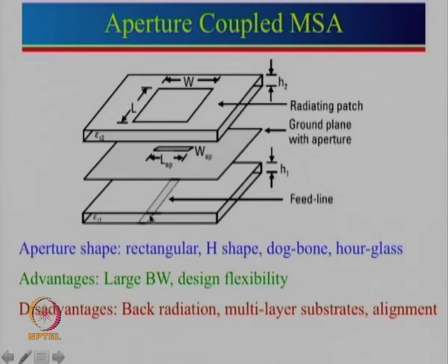So, now let us see what is really happening one more time. This is the microstrip line, and generally speaking, if you look from this side, this one will be roughly λ/4 extended, so that the maximum coupling can be done through the slot. Now, it is not always necessary that you always take λ/4. Sometimes if the coupling to the top patch here is too strong, you can either reduce the slot dimension or you can change the length of the microstrip line also.